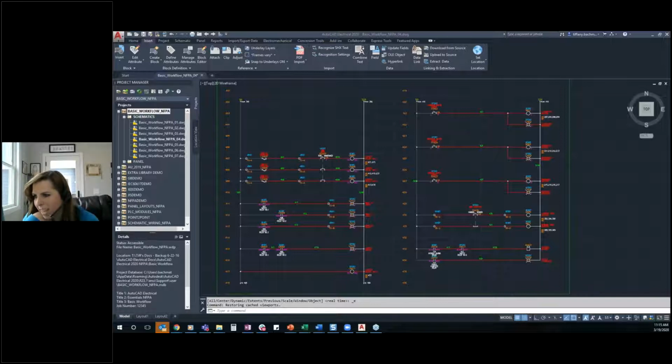Matt, I think the next one is you too. Okay, anytime I modify my local file, I get an unknown status from the Vault add-in on the project manager. Vault shows the correct status. So the only time I've seen unknown status is if quite possibly your workspace is different than what Vault is saying your workspace should be. So all I can say here is make sure you're logging out, log back in with Vault, the Vault client, as well as inside your AutoCAD session for Vault as well. That might take a little bit of troubleshooting.